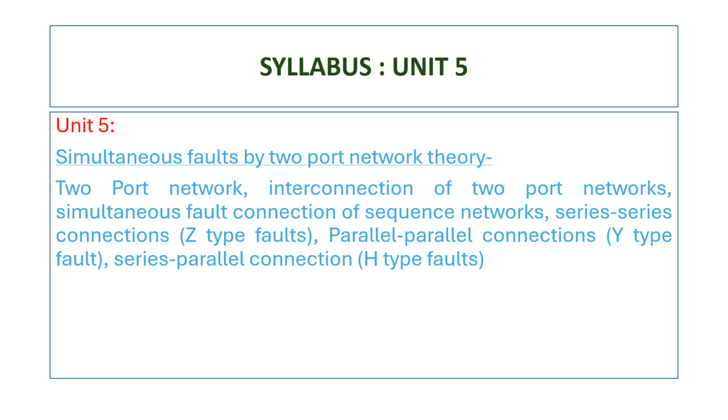Along with this, we are going to learn interconnection of two-port network. It is just an extension of two-port network theory. And using this concept of interconnection of two-port networks, how it can be used for fault analysis of simultaneous faults. So we have three simultaneous faults here: Z type of fault, Y type of fault, and H type of fault.